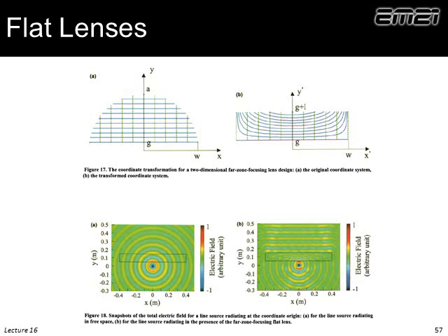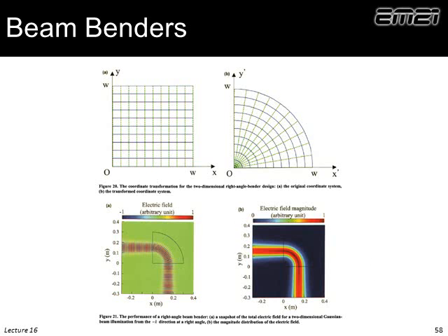Here's another version of that where we move the dipole source outside our metamaterial lens. And so the dipole source radiates like a dipole on the outside, and it flattens. So we could actually use a little tiny antenna that wouldn't be highly directive, let that pattern pass through this lens type of device, and it could collimate that beam for us. Bending beams, we're doing a lot of that here. We are using spatially variant self-collimation to do that, but we can also certainly do it with transformation electromagnetics.